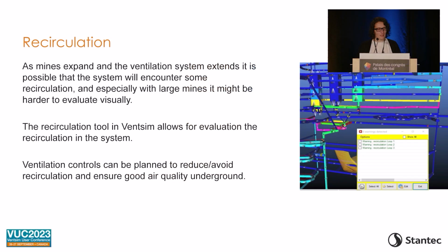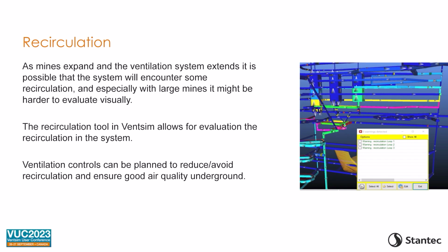My next benefit is looking at recirculation, especially when we have a big mine that keeps on extending, advancing and changing. It's easy to forget about recirculation, but in Ventsim there's a tool which doesn't take that long to run, and once you run it, you can see areas of the mine which are recirculating, and in some cases, it might be just because of how Ventsim models it.